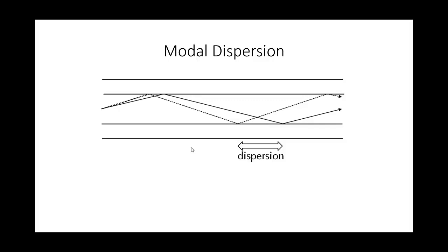Single mode fibre, or SMF, with smaller diameters such as 9 microns, for use with longer wavelengths of 1310 or 1550 nanometers, is known as single mode fibre because the light can only take one path through the core of the fibre. As there is no modal dispersion, longer run lengths of cable can be achieved, particularly when the light source is a powerful laser. Run lengths of 10 kilometers can be achieved. However, SMF cable is more expensive than MMF cable.